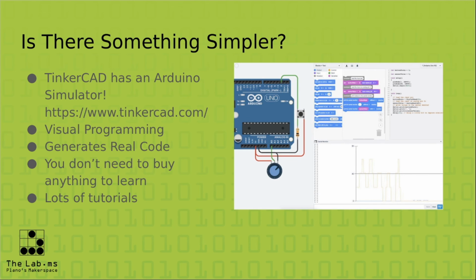All right, is there something simpler though? Yes, there is. There is a tool called Tinkercad, and it was originally designed as a 3D modeling tool, but they've added this Arduino simulator to it. What's great about this Arduino simulator is that it is a complete graphical environment. You can even do visual programming. So rather than writing lines of code like we saw in the last slide, you can actually use these code blocks.